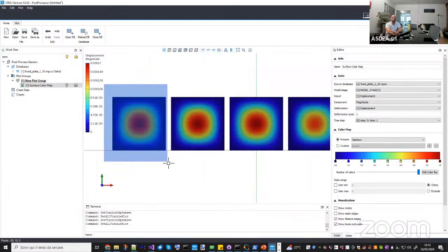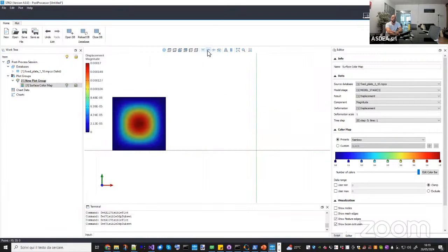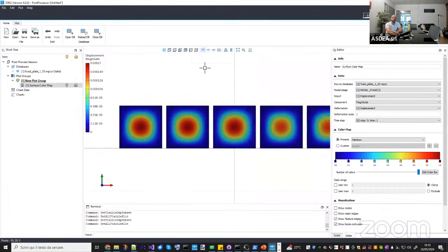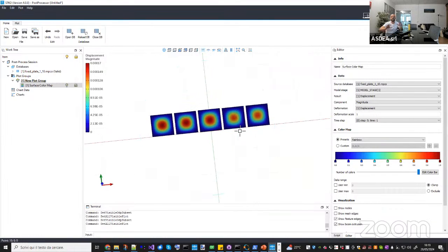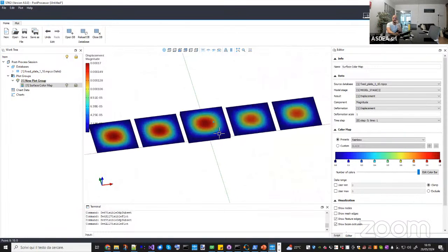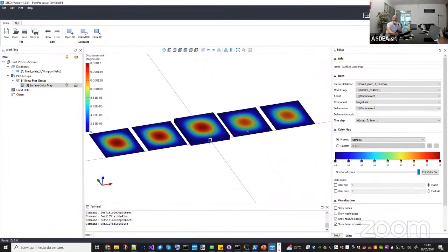So I isolate this one, and I have 1.7, exactly as the solid element, okay? So the point is that 1 to 10 is a very strong limit. If the thickness is even higher than that, okay, you cannot rely on a thin shell element.